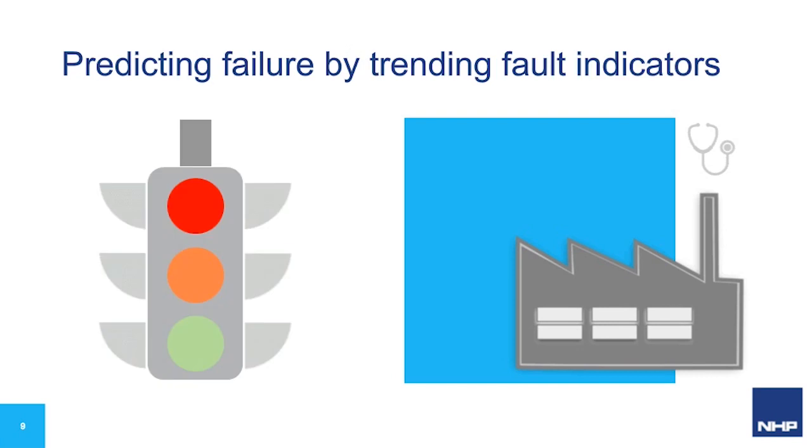So, predicting failure by trending fault indicators. Well, faults almost always propagate in a similar manner. First, they instantiate or worsen until above some level of detection. Second, they slowly propagate until end of life. How long this takes is dependent on conditions. If a machine is overstressed, under-lubricated, or overheated, this step could be skipped entirely to step number three, deteriorate exponentially until failure. Continued operation above an alarm level may result in damage to components other than the wearable component.